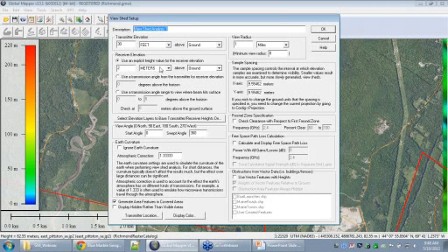We can do a visual line of sight about 2 meters off the ground for an eyeball height if you're really tall. There are some other options where we can fine-tune that. And these other options are going to be probably a little more useful to those of you doing things like radar or cell phone network planning or other radio network broadcast planning. We can set the view angle there so we can sweep around in particular directions. And again, all of those options that we have for analyzing the broadcast frequencies, such as the Fresnel zones and the Earth's curvature for the 4/3 coefficients.